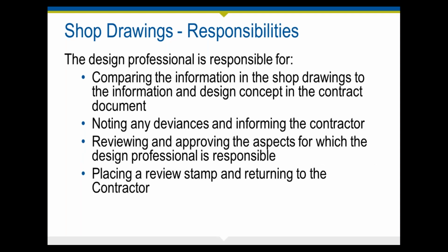So once you get that, you are then comparing the information in the shop drawings to the information and design concept in the contract document. Typically, you note any deviances and inform the contractor, and you should only review and approve the aspects for which you are responsible. So if you're receiving shop drawings that don't relate to something that you have asked for, that isn't a requirement,